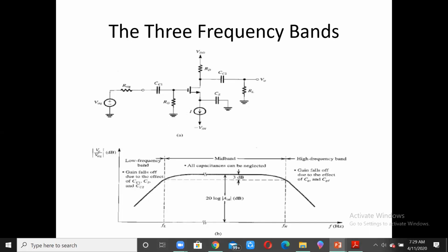So this gives us the common source, or what is known as the CS amplifier, with the coupling capacitors CC1 and CC2, which are used to separate the DC from the AC, and then you have the bypass capacitor, which is the CS capacitor, used for bypassing as well. That just means that at the time of amplification, feedback is not going to work out very well. But for the DC, the feedback is considered so that stabilization is improved.